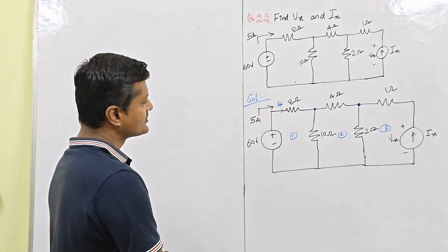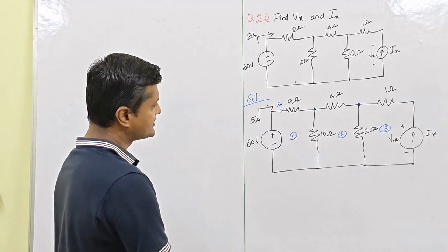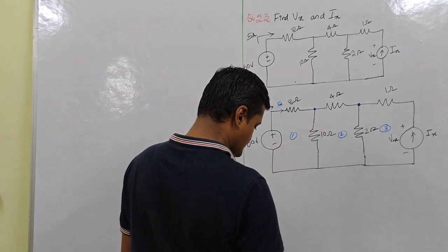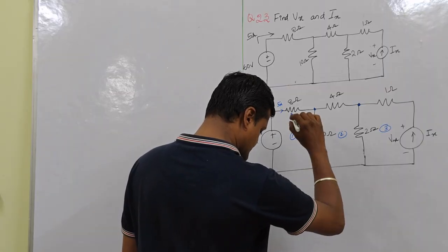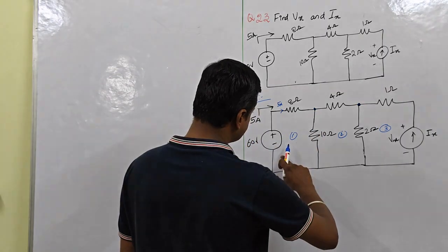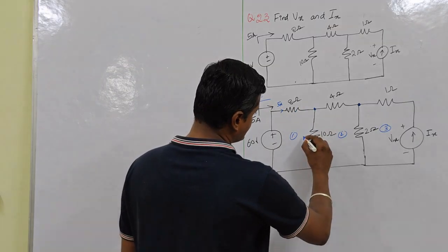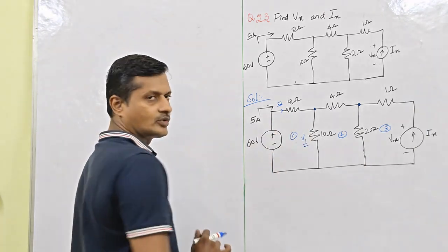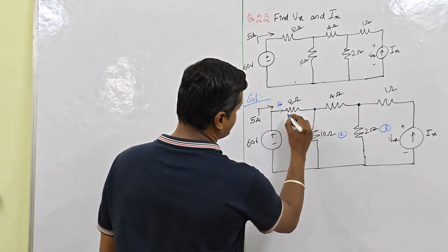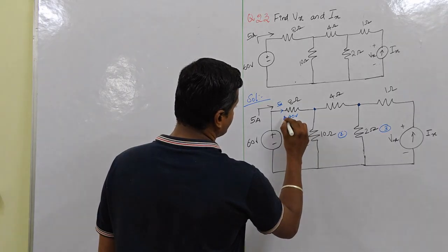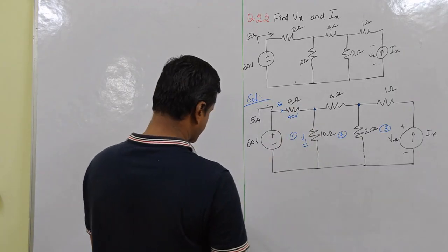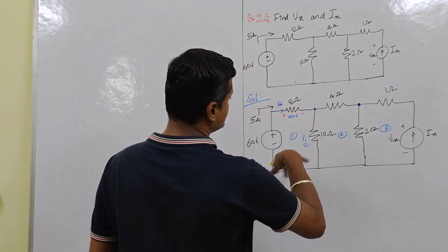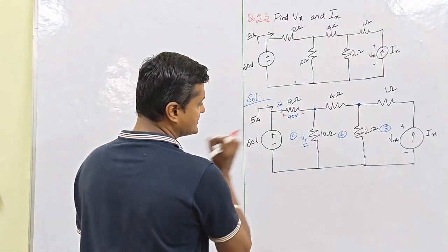Okay, right. Then how to find the value of 10? So 5 amps, so what will be the current flowing through this? We have to find that by applying Kirchhoff's voltage law. What will be the voltage across this? V1, right? 60, 10, and we have to find V1. So by using this, do we know the voltage across this? So 5 into 8, we have 40 volt, plus and minus we get. So by applying Kirchhoff's voltage law we can get the value of V1.